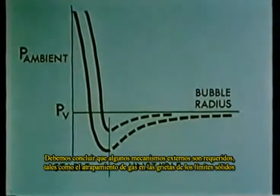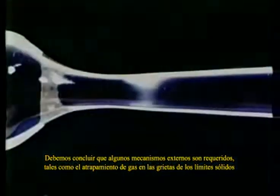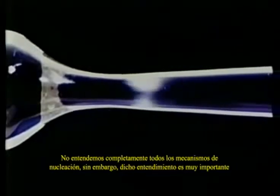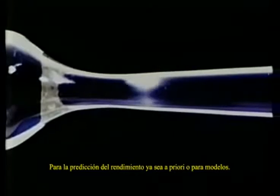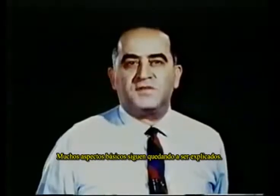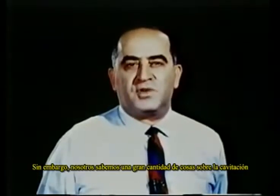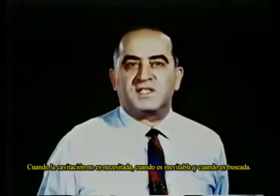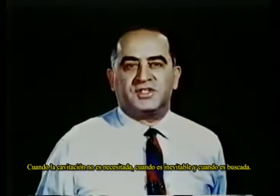We must conclude that some external mechanism is required, such as entrapment of gas in the crevices of solid boundaries or on dust particles which contaminate the liquid. We do not fully understand all of the mechanisms of nucleation, and yet such understanding is very important to the prediction of performance either a priori or from models. Many basic aspects still remain to be explained. Nevertheless, we do know a great deal about cavitation, and its effects on performance of machines can be predicted fairly well, when cavitation is unwanted, when it is inevitable, and when it is sought.